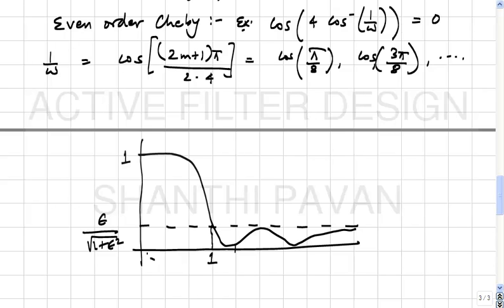And 15 years ago, people thought gigahertz was RF, okay. But today the dimensions of devices have reduced so much that on an IC, whether you're designing circuits at 1 gigahertz or 3 gigahertz, it doesn't really matter, because at 3 gigahertz the wavelength is about 15 centimeters or so in a dielectric, whereas the IC sizes that you're talking about are a fraction of a millimeter.